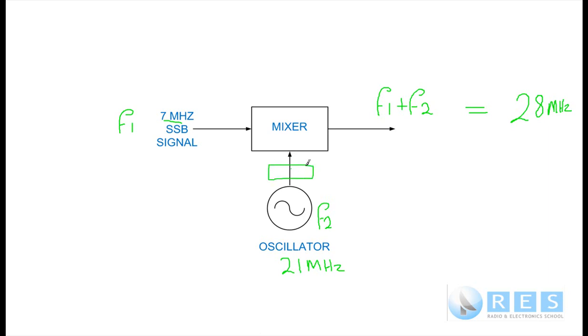It's not normally shown on circuits because it's presumed to be there, and it's just another amplifier, and it's called a buffer. A buffer amplifier is the full name. It's usually just called a buffer, and even though it's not shown on block diagrams, after every oscillator there will be, if it's a well-designed radio, a buffer stage. The function of a buffer stage is just to lift the very low power of the oscillator up to a usable level before we send it to the mixer.